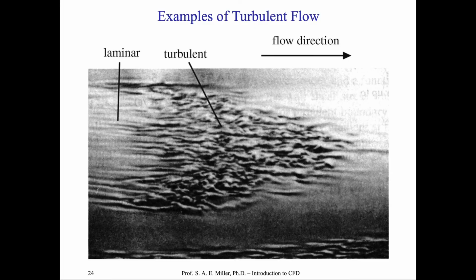Let's now take some time to look at some examples of turbulent flows, just to get a better idea of them. And of course, many of these are from the book of Van Dyke. Here's a flow which transitions from laminar flow through a transitional region into fully turbulent flow, which then breaks down again. This is generally a transitional flow because it goes laminar to turbulent and decays very fast. It never really forms fully developed turbulence. Fully developed turbulence can only be classified as a wave number spectrum of all scales between, of course, the Kolmogorov scale and the integral scale.